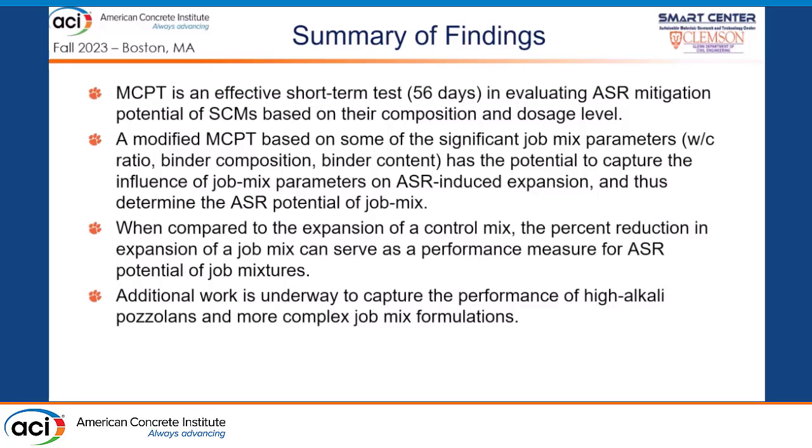Like I said, I didn't get to share it here, but we also have some other work going on looking at more complex job mix formulations where you have multiple aggregates that are reacting, as well as SCMs that are releasing alkalis. I should also mention there is a lot of talk in these meetings about SCMs releasing alkalis and how they contribute to the alkali loading.